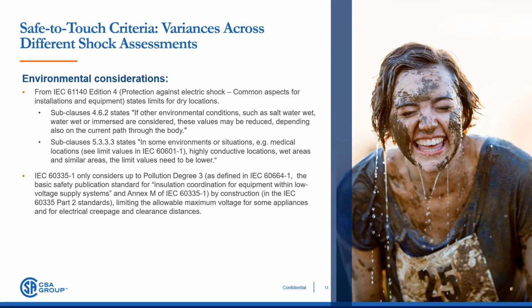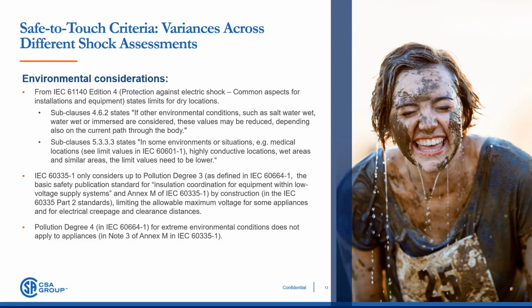Pollution degrees are defined in IEC 60664-1, the Basic Safety Publication Standard for Insulation Coordination for Equipment within Low Voltage Supply Systems, and Annex M of IEC 60335-1. However, extreme cases of conductive pollution, as categorized by pollution degree 4 in IEC 60664-1, are not addressed, as it has been deemed by the committee as not applicable to appliances, in Note 3 of Annex M in IEC 60335-1.